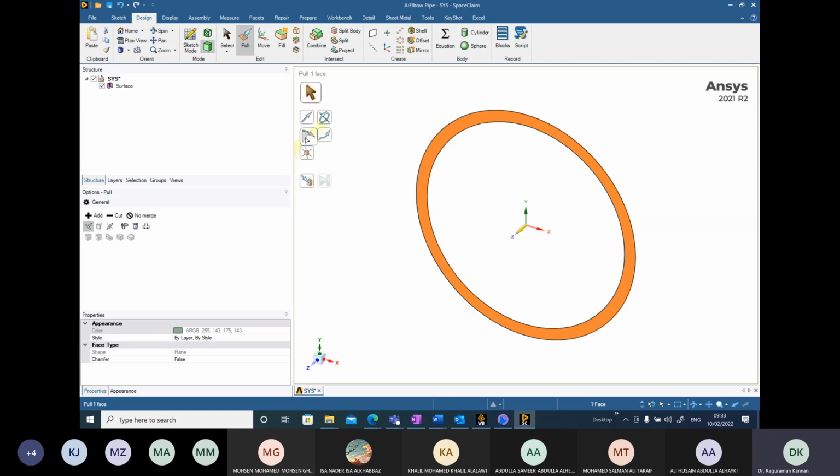This is the pull direction. And you can also rotate it with respect to a particular axis up to a certain limit. Instead of rotating it 360 degrees, I can rotate it to a particular level and leave it. Okay. There is also the sweep option. This is the option I'm going to use. When I move my cursor on the sweep option, it clearly shows select the lines or edges along which you want to sweep the selected face or edges. You can select multiple connected lines and edges that form one trajectory.